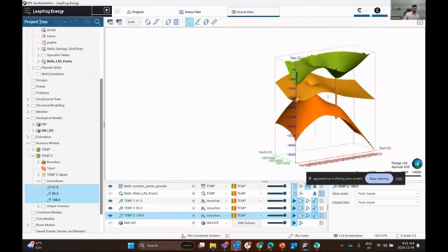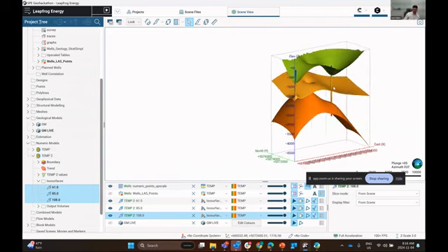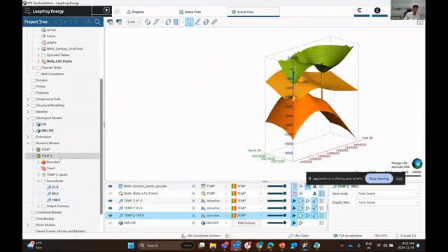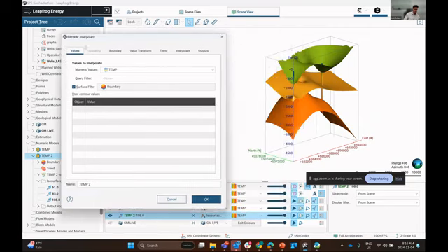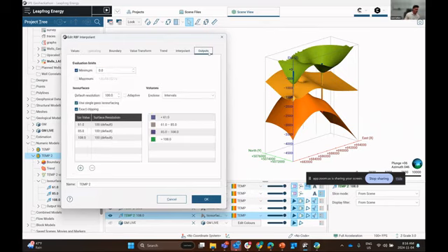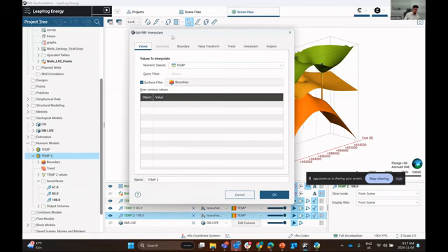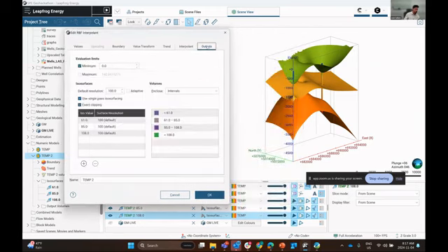And I'll quickly show you how you can adjust this RBF interpolant, leaving about 10 minutes for questions. So if we double click the interpolant that we just generated, the first step is likely to adjust the outputs. Depending on the isosurface that you're most focused on, I double clicked the temp 2, went to the outputs tab, and I'm going to add new isosurface values.